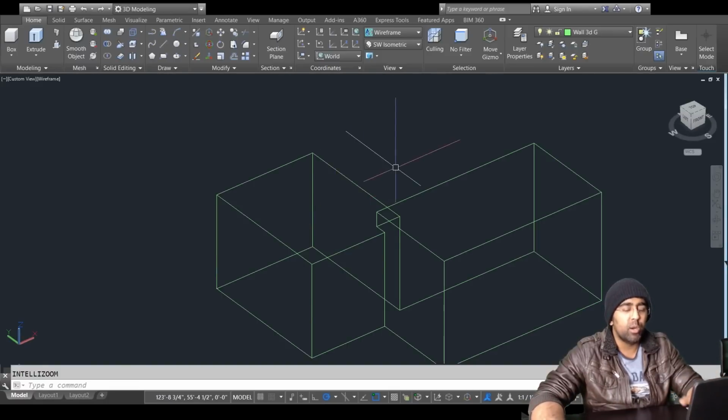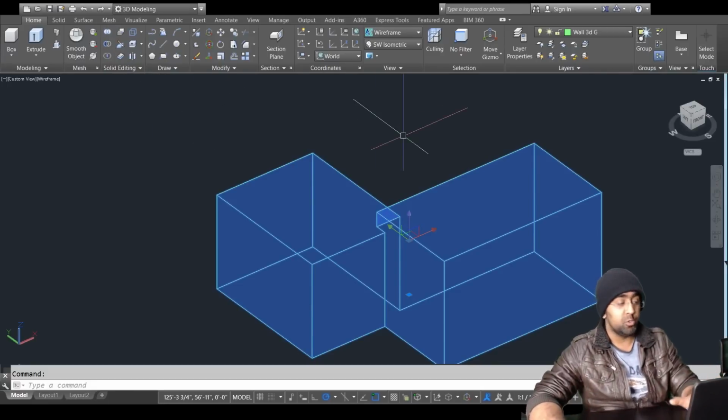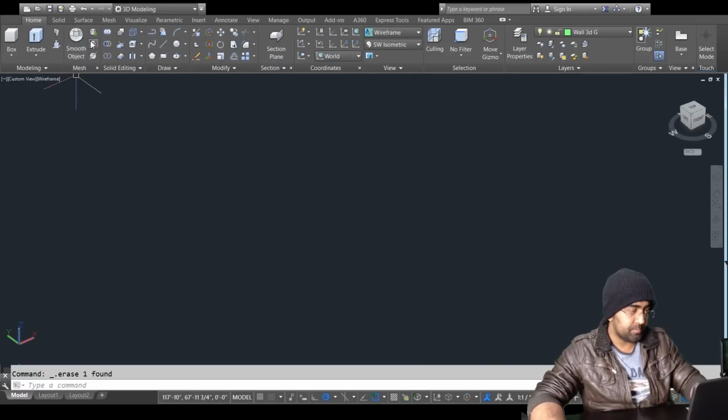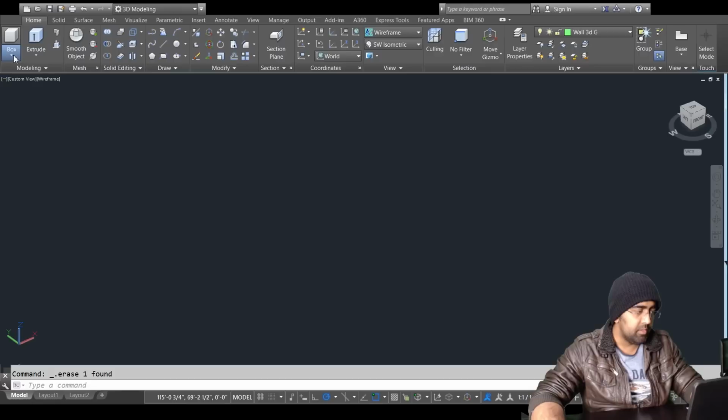But now in AutoCAD 2017 or 2016, there's a lot of features in solid modeling, so you don't have to use those commands as much as you used to. Okay, so let's get rid of these boxes now. So we have seen these three commands. Now let's look at extrude. Extrude, loft, revolve, and sweep, these four commands, are all extrusion type commands. The first commands we have are cylinder, cone, sphere, pyramid, wedge, and torus. We have these built-in objects, so we can make them by selecting them.